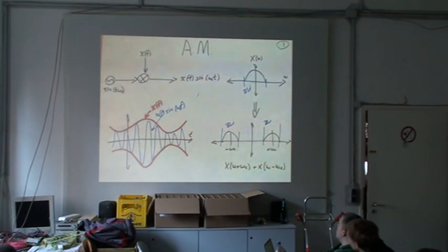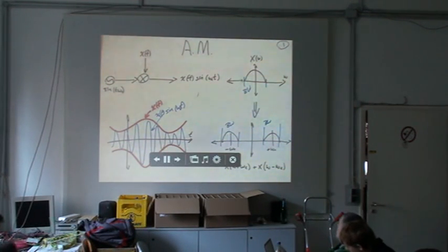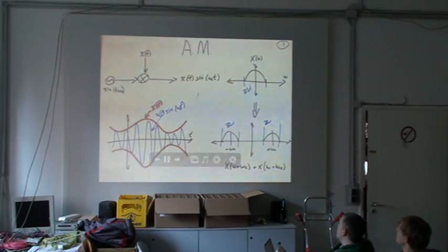For a real valued signal, the spectrum of X is also symmetric about the zero frequency. So one side of the spectrum is a mirror image of the other. That means in the upper right there's a two-way symmetry, but down here what you actually have is four-way symmetry, because the original spectrum is symmetric and now you've made symmetric copies. While this seems like really elementary stuff, all this spectral symmetry becomes really important in the design of the radio modem inside OpenBTS Layer 1.